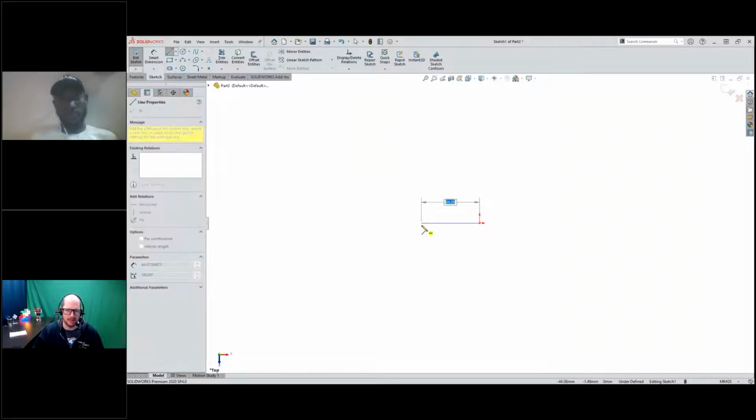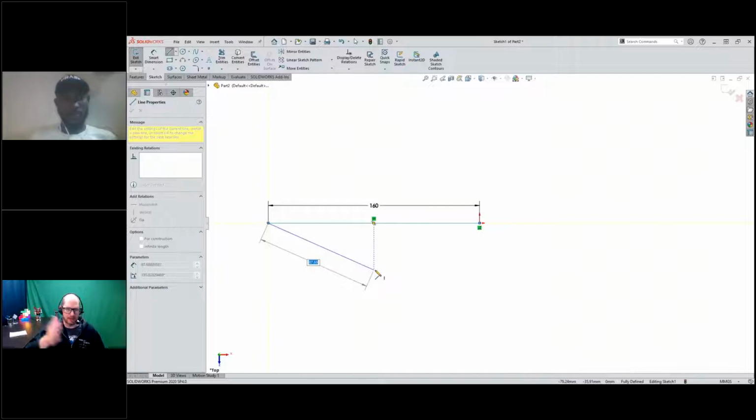whenever you're creating sketches. And this is a great time saver in SolidWorks because you don't have to go back and re-add the dimension, and because you know right away that you're sketching at the correct size. So there's really two benefits there.